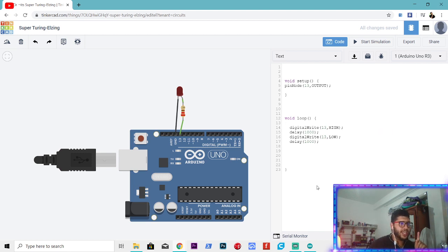So what we need to do is put a delay. We tell the Arduino, hey, wait for a few seconds or milliseconds. It depends on your needs. For example, if you are working with multiplexing, where you have a lot of LEDs, a matrix and that kind of stuff, you want the delay to be small.